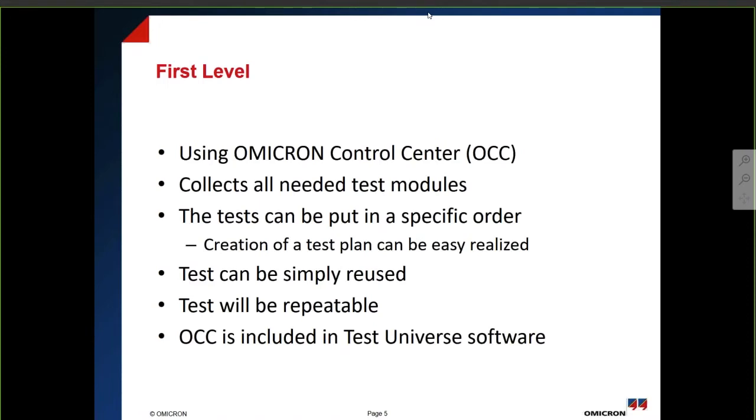So as we said, you will create your OCC file for that relay, and this kind of test you are going to test, like pickup, drop-off, timing, and directional characteristics for the system. Based on this, you have to be familiar with the modules, what each module can do. For the pickup, you are using the ramping. For the drop-off, also we use the ramping. For the timing, you can use a state sequencer if you would like to test so many cases and so many fault points.